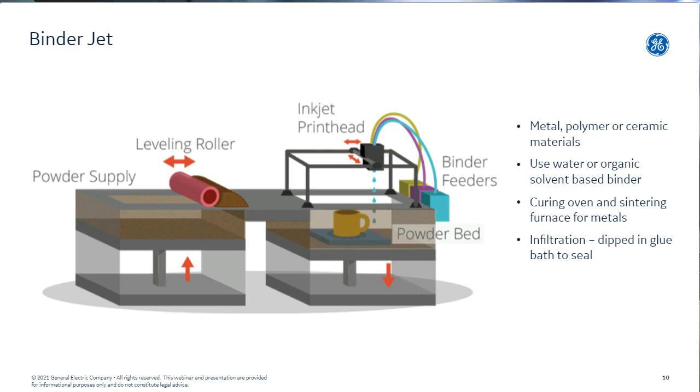This resin needs solvents so that you can transport it. The solvents can be either water-based, which is not of very high concern, but it can also be based on a flammable, ignitable substance. And you need a lot of that. Secondly, the process itself is fine, but you then take it out, and then you need to cure it. You need to put it in an oven and to shrink it in a way. Also, that process maybe can generate additional hazards like fumes or volatile organic compounds. So you need to understand it a little bit.